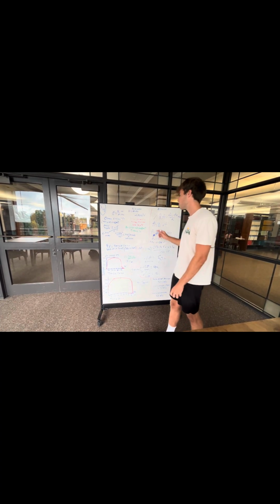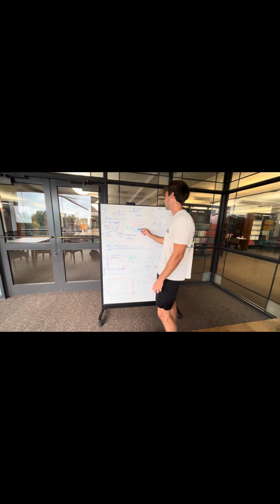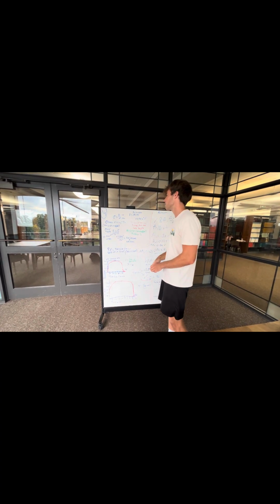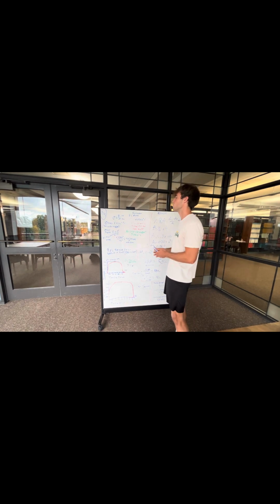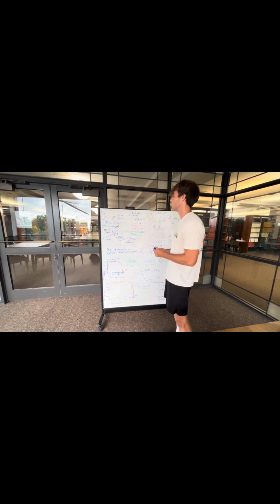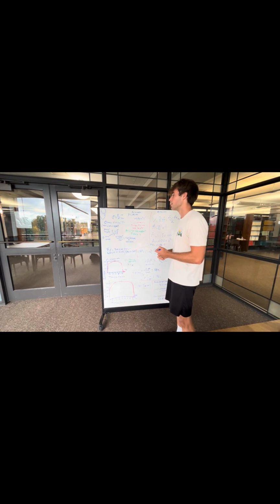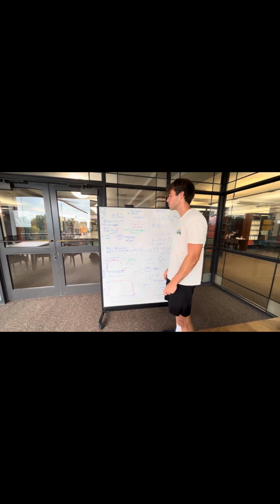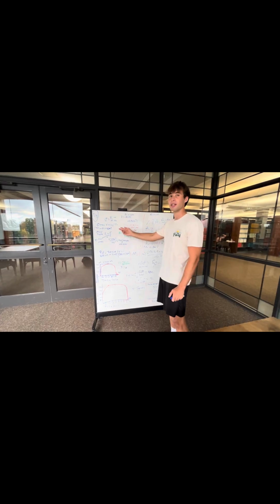So if we plug in A, this number here, and F, which is also this number here, to find the strain, we have to find the stress first. Stress would equal 6.25 times 10 to the 12 pascals, and typical stress would be around 1 to 2 gigapascals, which is nowhere near this number.